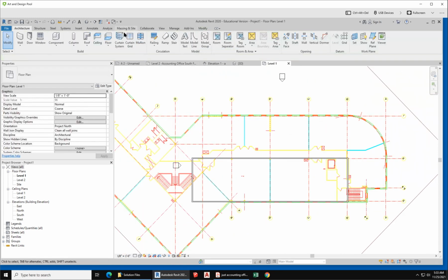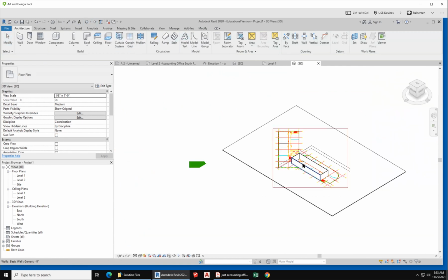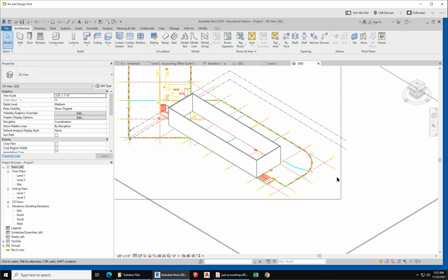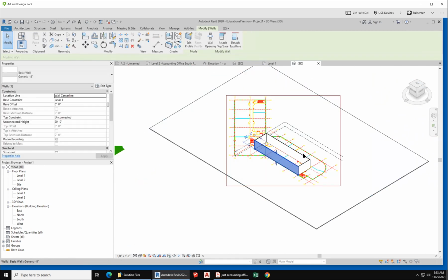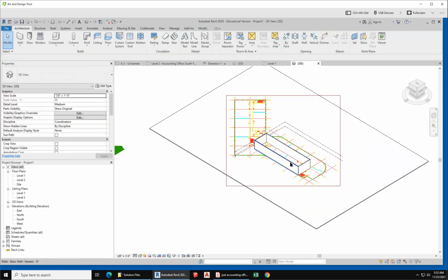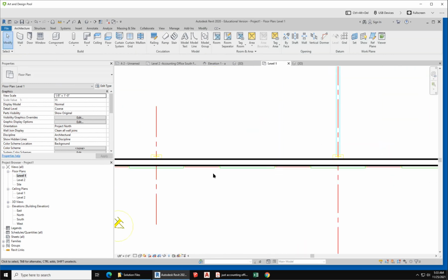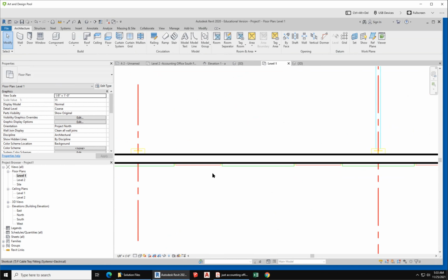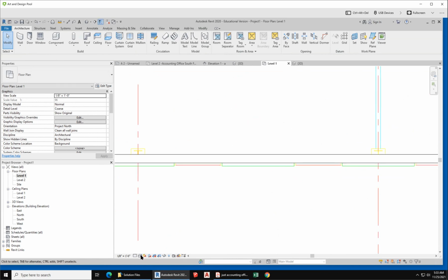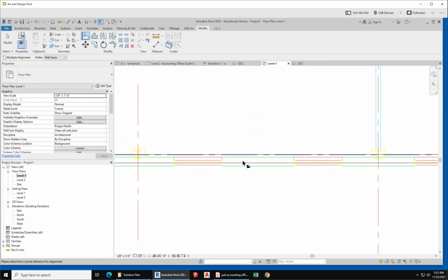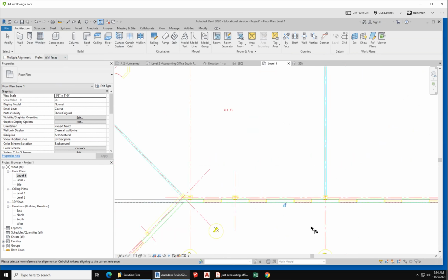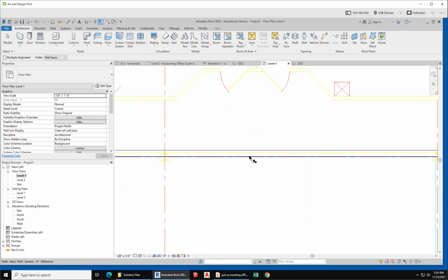So if I go to my 3D view, what do I have so far? CAD drawing, floor, 4 walls, right? So I wanted to put windows in there to go to that floor plan. Remember, I'm just drawing into the line. Let's turn off line weight and make this wireframe. Line, wall, align wall.